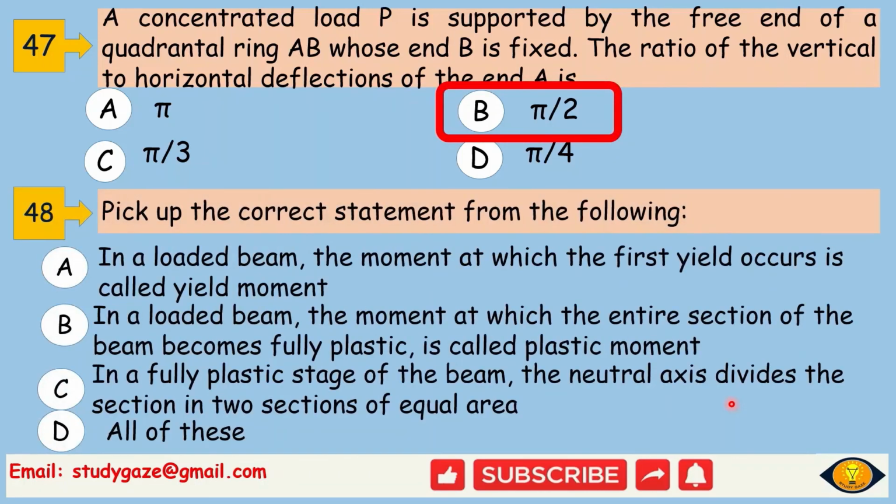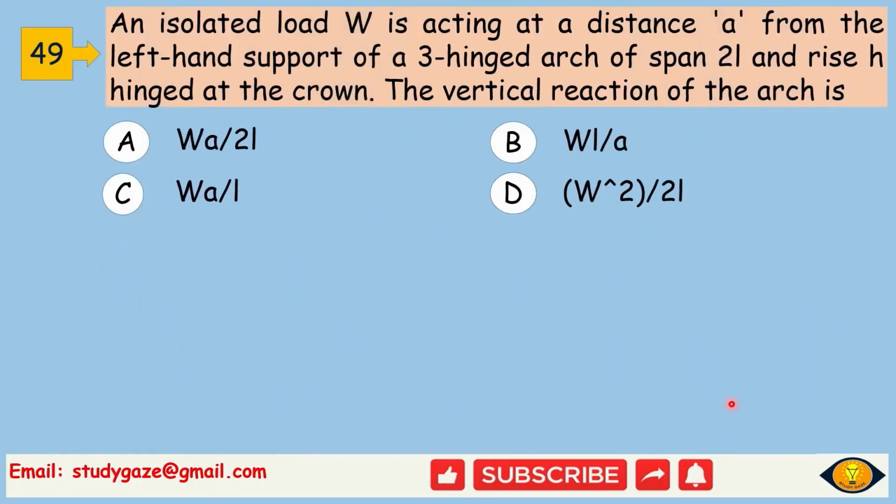Next, pick up the correct statement from the following. So the correct statement is all statements are correct. Next, an isolated load W is acting at a distance a from the left hand support of a 3-hinged arch of span 2L and rise H, hinged at the crown. The vertical reaction of the arch is Wa by 2L.